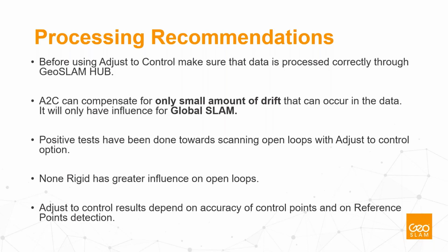And obviously reference point detection is important, because if some of the reference points are not detected, or not detected correctly because of the movement during that detection period, then those control points might not be good to use. That's why it is good to have more control points than needed, so that you can maybe play with excluding some of them from processing.